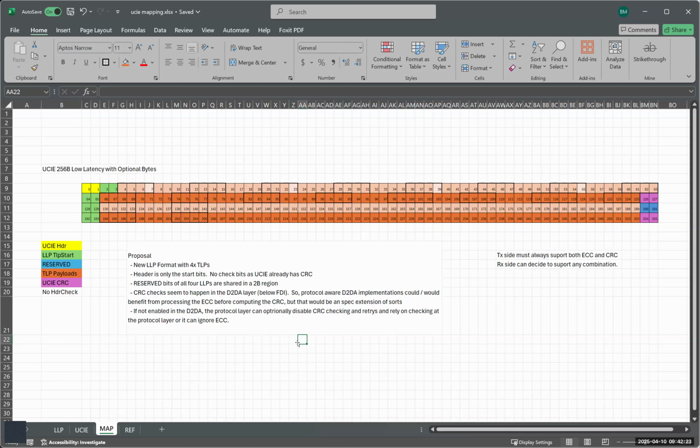So you end up with most of the error resilience benefit and potentially more performance. But it's a risk, right? Because you're not fully covered, and so you could end up with an unrecoverable error. But you'll get the CRC error either way from FDI, so you'll know if it's unrecoverable at the protocol layer, and you just have to be able to handle that from a system layer.